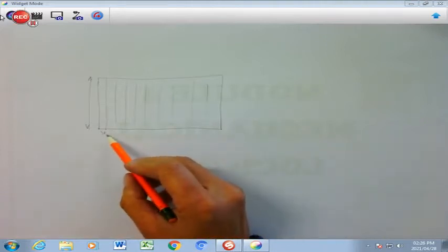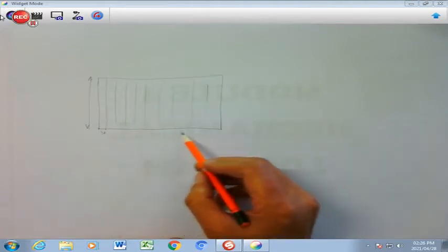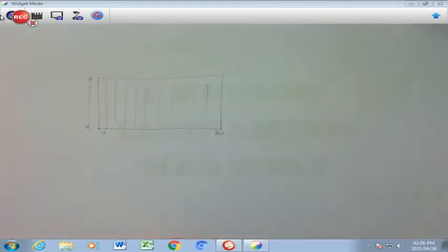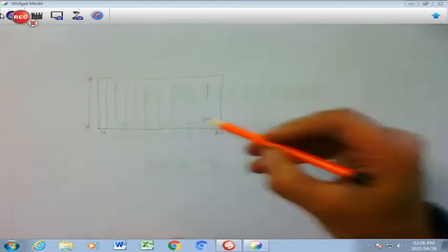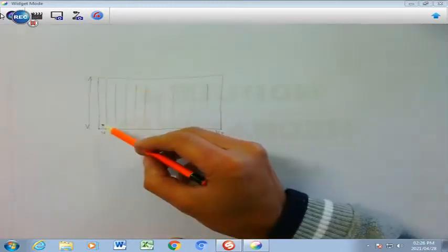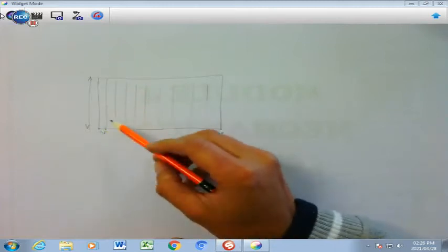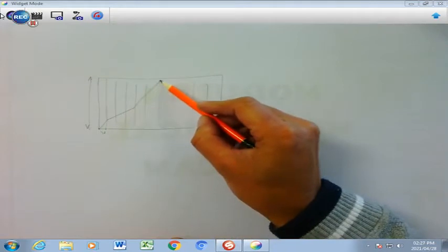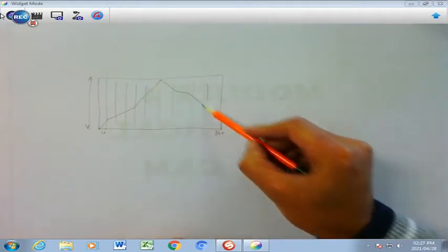You will have equal spacings of 30 running right to 360, which is one revolution or one circular motion. That is where we start, and you have to plot this cam displacement diagram with the basic information given to you.